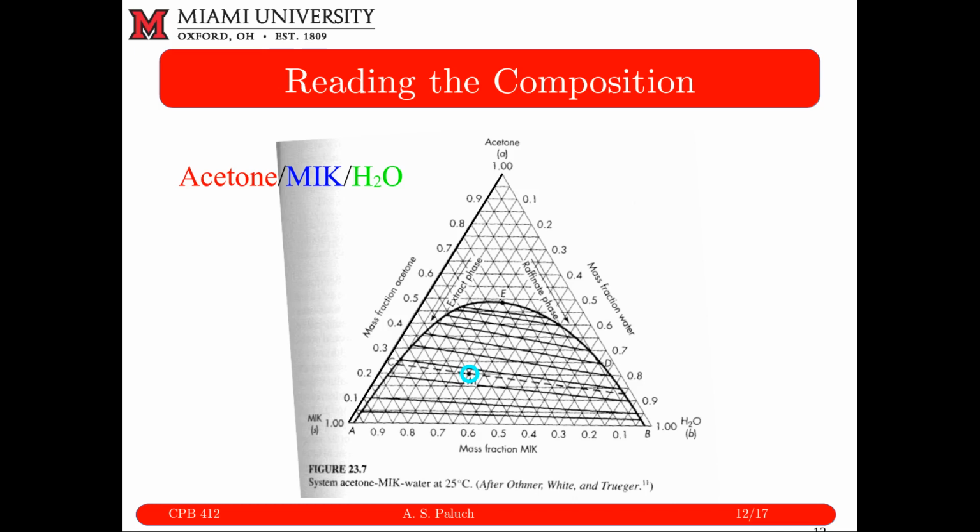Okay, so when we had our TXY and PXY phase diagrams, I just either drew an isobar or an isotherm, right, and life was good. We can't exactly do the same thing here, right? And the reason I can't is, if you recall all the way back to the beginning of the set of slides, temperature and pressure are held fixed, or constant, throughout this entire diagram. All right, so in terms of drawing isotherms or isobars, well, temperature and pressure are already uniform throughout.